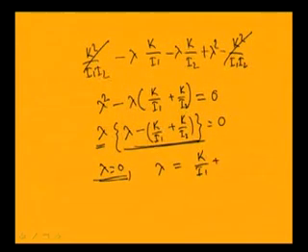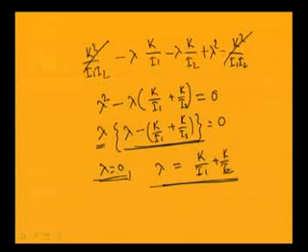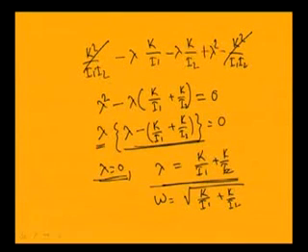Already you know in the previous class that this is a degenerate system in which one of the natural frequencies equal to 0, which you have obtained here, and the second natural frequency you are getting is k by I1 plus k by I2. So, this is lambda, so frequency will be root over this. So, your eigenvalues are 0 and k by I1 plus k by I2.